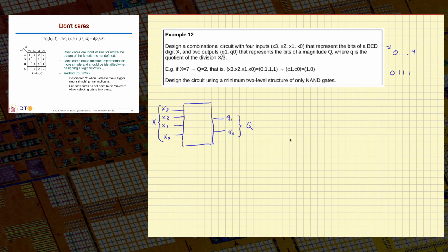Sometimes, and it's very common in more complex circuits, we define signals that can have multiple bits, so we have a more compact representation. So this circuit may have also been represented by saying that my input is number x, which is composed of 4 bits. So I cross the line here, meaning that it is 4 bits. Normally every bit is named by using a subscript, like in this case.